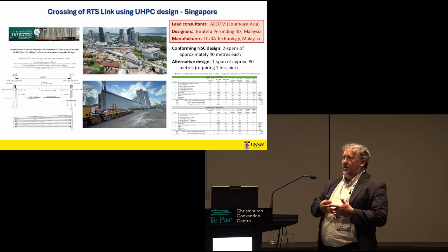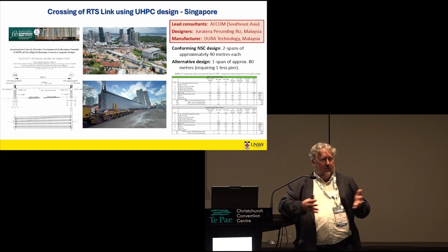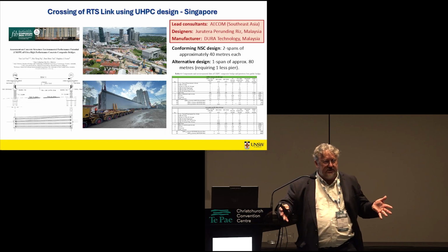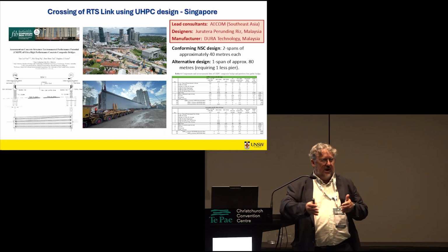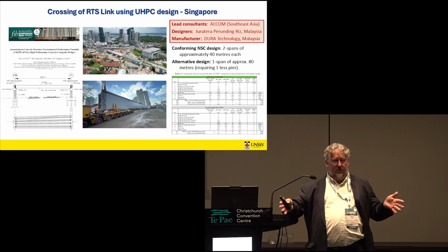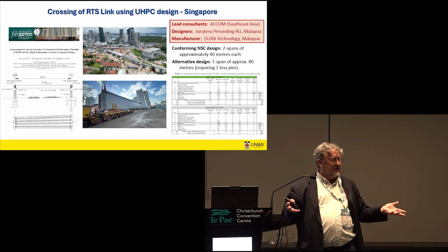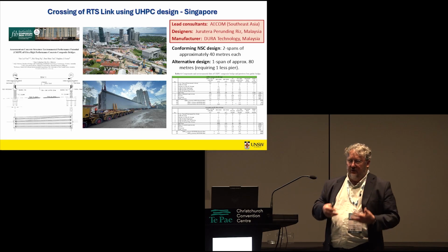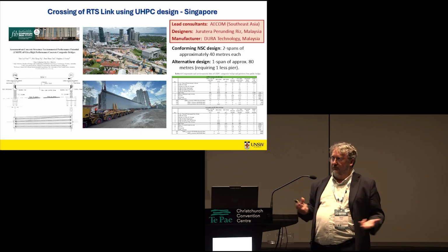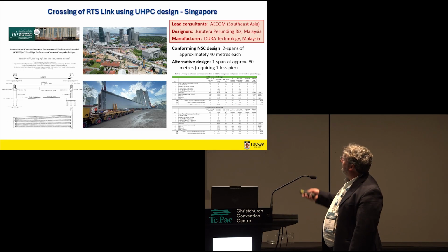Because the problem with simplified models is that when you change a system, design decisions change. So the thickness of a slab might change because you've got wider or closer supports to it. The piles change because you've got a lighter superstructure. So you need to consider the whole of the system. And this is in that paper. It gives you all the details, the full inventory of analysis and the life cycle calculations.